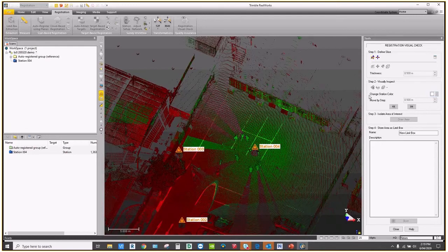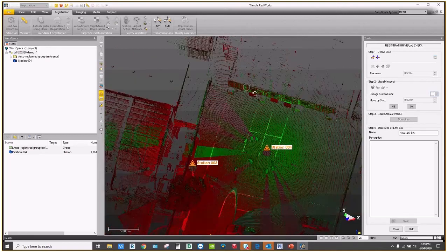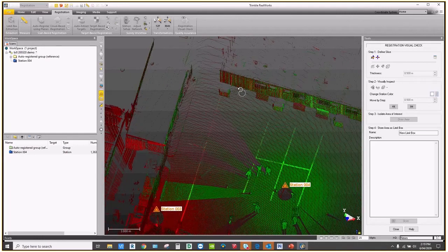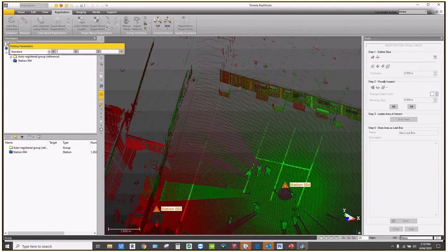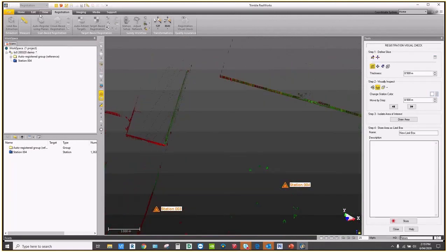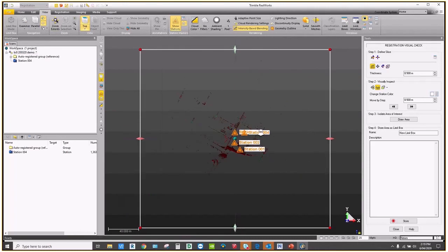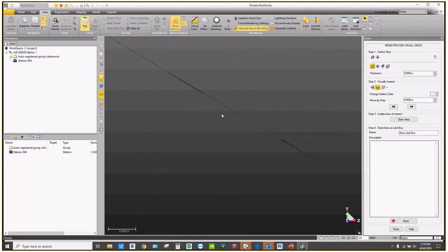So, if I just wanted to cut a slice through here to see that my two lots of data are lined up okay, you generally want a building or something like that. So I'll just hit that, and then I can analyse that a bit further, and make sure that we haven't got any shadowing or steps or anything else in the data, and that all looks really good.